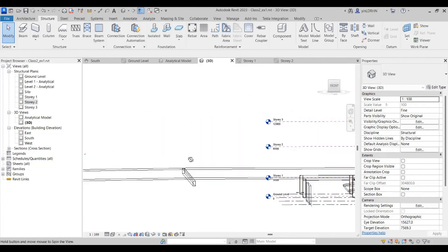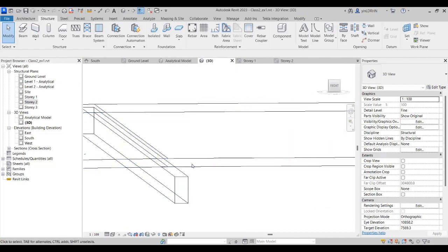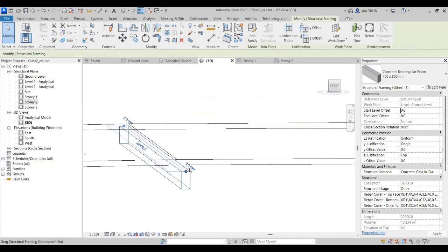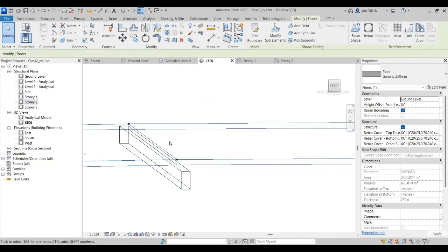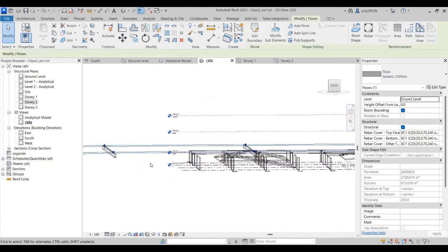So you can see right now the slab is supported on top of the beam, right? You can see the difference, right? So beam center line is below, slab center line is above, right? So the beam automatically lowers down and is made as a support, right? So mostly this tool is suitable for steel beam and slab because concrete normally we cast together, but steel beam, slab putting on top of the steel beam.